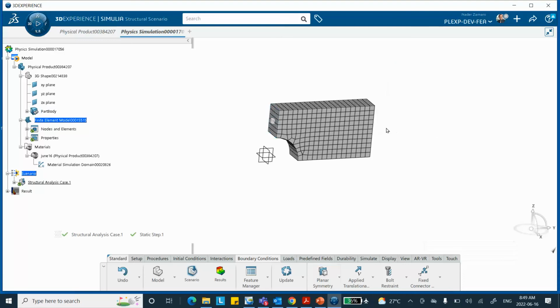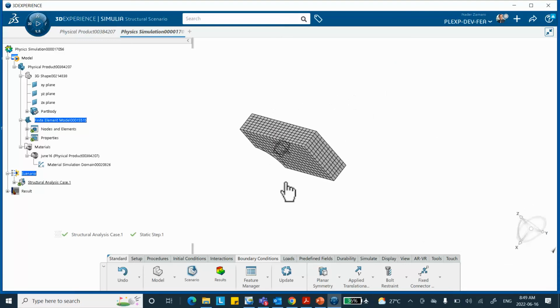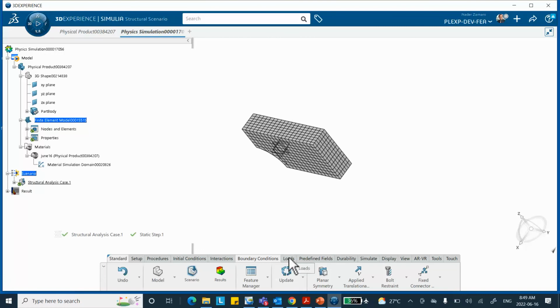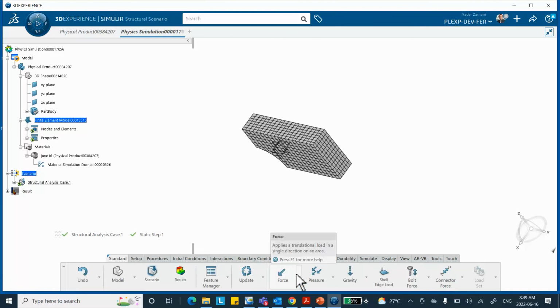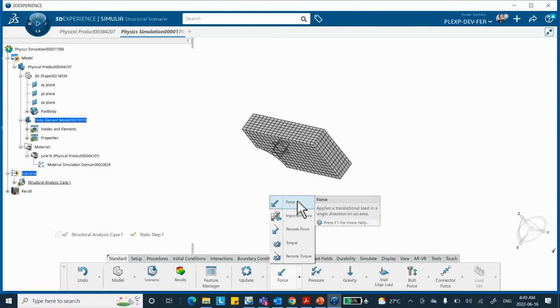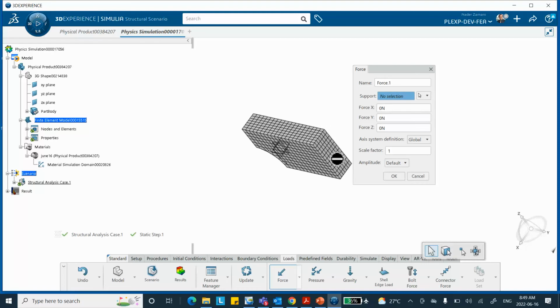Okay, good. And then the load. On the load, you can do force, you can do pressure, and there are other things you can do. So for example, let me put a force on that face, magnitude in the direction y, 1,000 pounds. Remember, if I'm doing a force, the actual force on the structure is 4 times this. This number that I put there is 1/4 of that 4,000, if it was 4,000 on the entire structure.